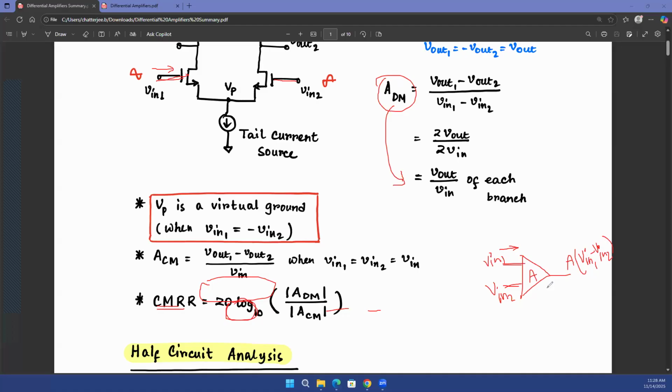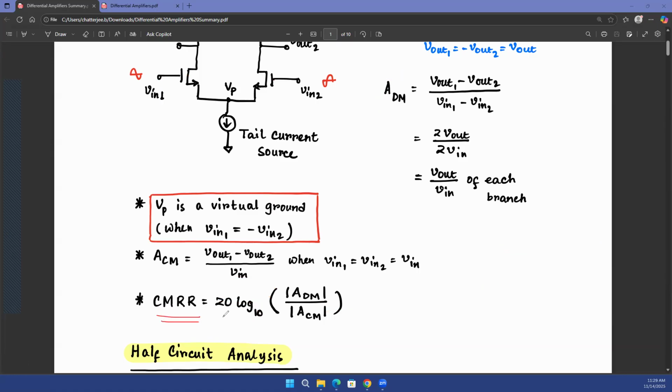That's the differential mode gain of the op amp again. And we just talked about the differential mode gain of the differential amplifier as well, which are basically the same thing, same concept. And that is because there is a differential amplifier inside your op amp. Now, there is a concept of CMRR, or common mode rejection ratio. What does that mean? If you take the ratio of differential mode gain over common mode gain, and again, these are both AC gains. There's no concept of DC here.